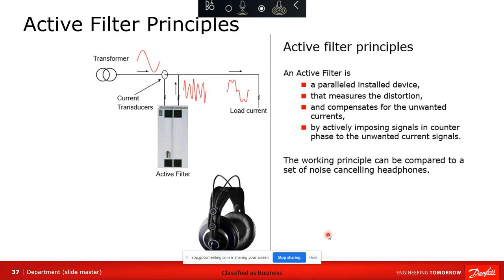These are excellent solutions if you have several drives and you want to spread one active filter across several drives. I did a job in New Jersey that was 8 100 horsepower NEMA 4X outdoor mounted drives, mounted over the aeration basins, connected right to the surface mixers. They didn't have any room to mount the drives in a building. With NEMA 4X, you don't have to mount it in a building, you mount it right outside.